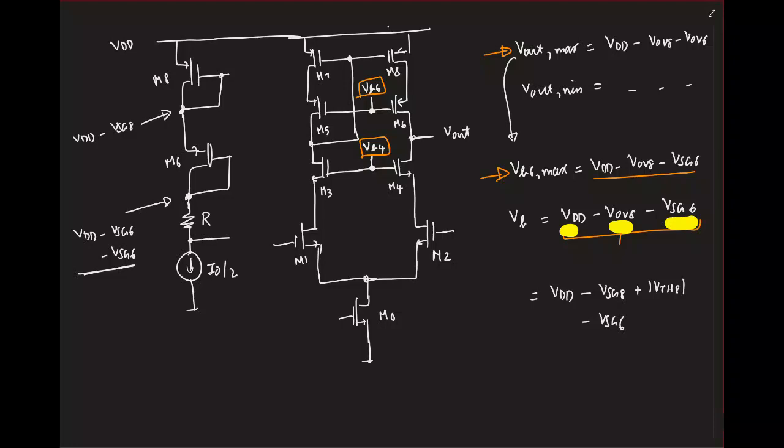Lower than that. You want a voltage that is higher than this voltage by a threshold. If you diode connect a normal MOSFET, again we'll have a gate to source drop, but we want it to be equal to a threshold voltage. You can connect a Zener diode, but Zener diodes are all nice in textbooks, man, but in ICs we don't have Zener diodes, okay?